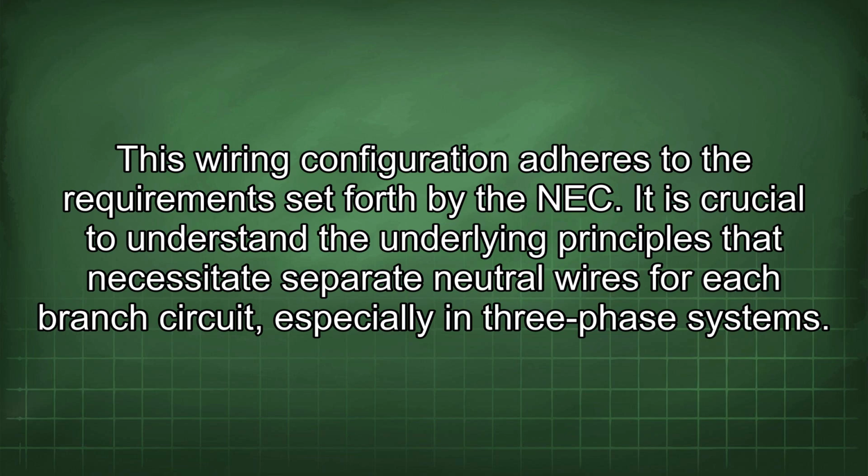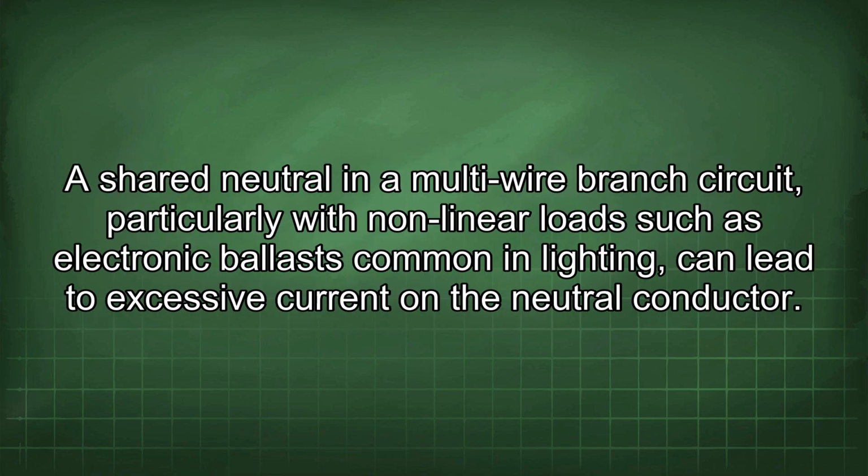It is crucial to understand the underlying principles that necessitate separate neutral wires for each branch circuit, especially in three-phase systems. A shared neutral in a multi-wire branch circuit, particularly with nonlinear loads such as electronic ballasts common in lighting, can lead to excessive current in the neutral conductor.